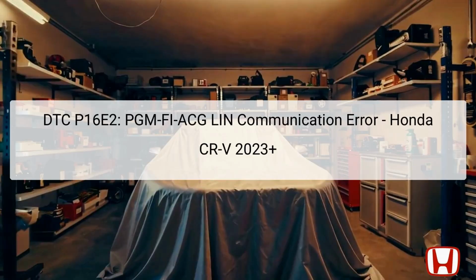The diagnostic trouble code, DTC P16E2, indicates a PGM-FI-ACG LIN communication error in the Honda CR-V 2023 and newer models. This code generally arises when the Powertrain Control Module, PCM, fails to receive necessary signals from the alternator via the local interconnect network, LIN. The alternator plays a crucial role in charging the vehicle's battery and powering electronic components. The LIN is a communication network that allows various vehicle components to exchange data.